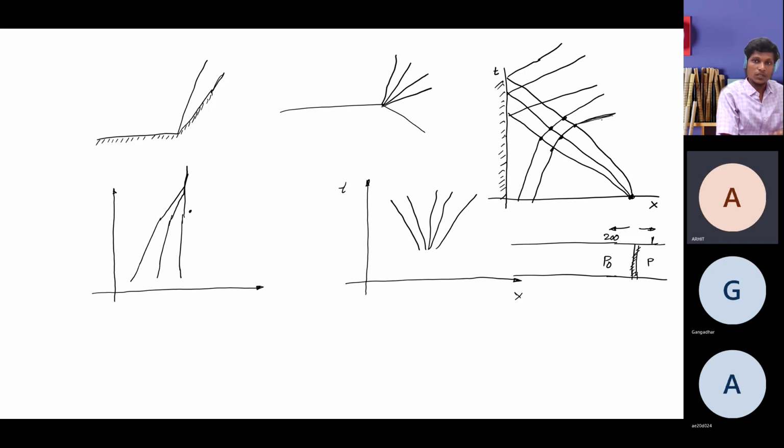Characteristic waves are there, those act as waves, but physically whether it is present or not, you can mathematically represent that, but this does not create any influence on the flow field. In case of expansion waves, even here in the compression corner, you can draw some lines like this. This is the expansion fan. The characteristic lines you can draw like this will create a nonlinear family of curves. A very curvature kind of thing will happen here.